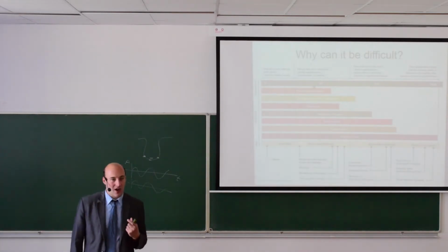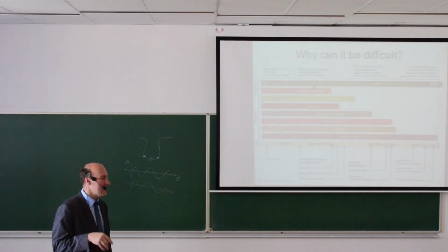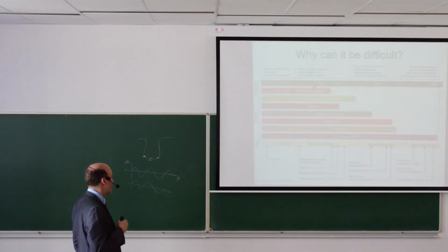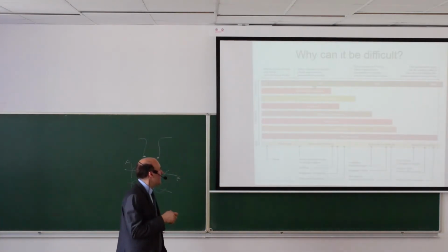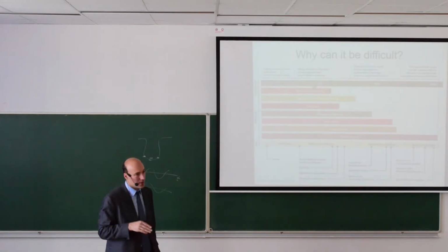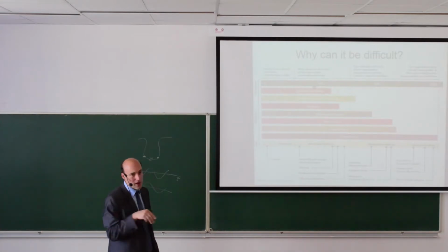What technologies are available? We can measure with mechanical devices. It can be some float, it can be a lid that we just open and we look inside, see ourselves what is the liquid level. We can measure with capacitive changes or radio frequency signals. We will see ultrasonic in details. We can measure differential pressure, a radar, or laser or nuclear sensors.